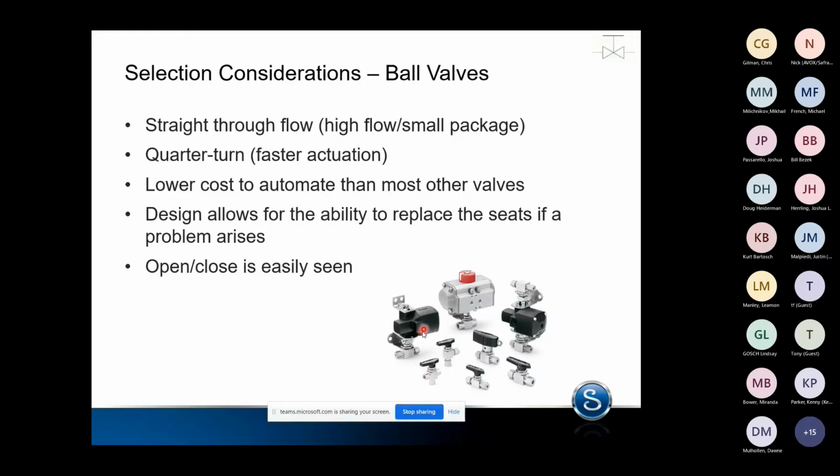And with most actuators, there also is an ability to see that as well. So for this style of actuator housing, there's actually a little puck on the top that rotates with the valve stem. So right now we're in an open condition. When this actuates 90 degrees, these little notches in the actuator are going to flip, and that's going to identify it as closed. It's a little bit tougher with these, unless you've been staring at them for a while, to identify these as open or closed.